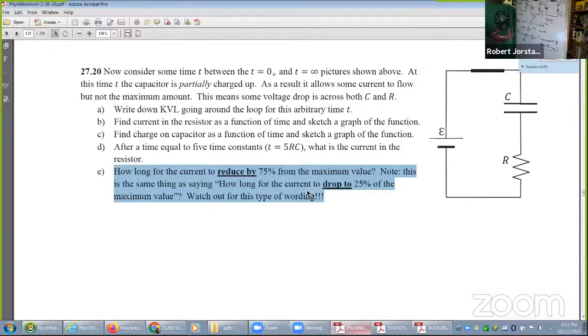And then in practice, in electronic circuits, a lot of times R might be a kilo ohm or something, but C could be something like nanofarads. So what's kilo times nano? That's like a microsecond, right? And so it only takes 5 microseconds to reach 99%. So you could see that very rapidly, this approximation is very good.